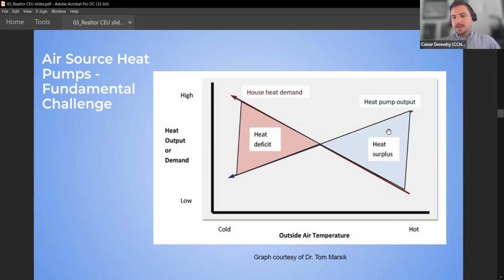But over here in this heat surplus area, which could happen over here in the cold, but I'm using this side as an example, you'll have trouble with the machine operating on an efficient cycle. It'll basically run in starts and stops. If you can imagine warming up your car in the winter, if you had to start it 4 separate times before you actually got in the car, you might start to wonder, am I putting some wear and tear on my vehicle? Same kind of concept happens if you oversize a heat pump. It just doesn't get a smooth cycle going.